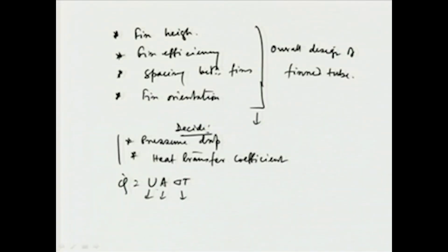And therefore the rate of heat transfer becomes less, because the rate of heat transfer depends upon the area, U and delta T. Delta T, as I told previously also, cannot be independent, it is decided by the external world, and there is a maximum value of U that can be obtained by changing the flow rate. Even by making very high flow, you can obtain only some maximum U, and there are also flow rate limitations, the cost of pumping or cost of compressor, all these things have to be taken into consideration.